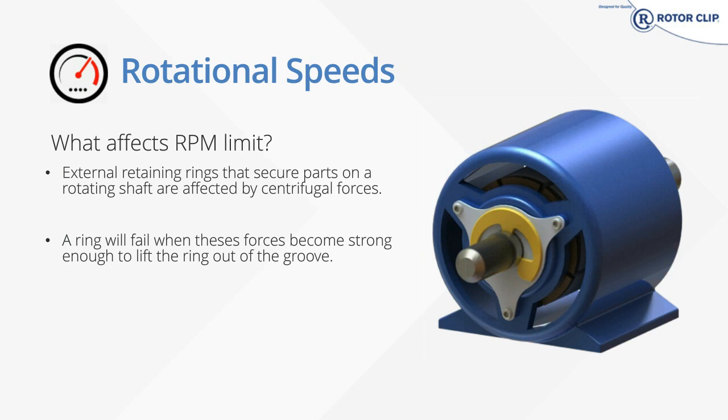From a design standpoint, a tapered section ring will help to improve radial force, as the RPM limits are directly related to spring force remaining in the ring. The easiest way to picture this is if you take your thumb and your index finger and try to pinch them together, that's the forces you're seeing on a ring, and as you open up, that's kind of the action you see the other way around.